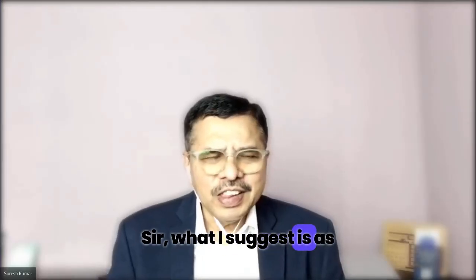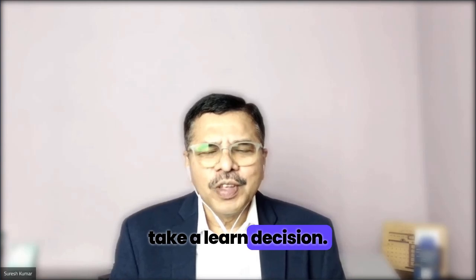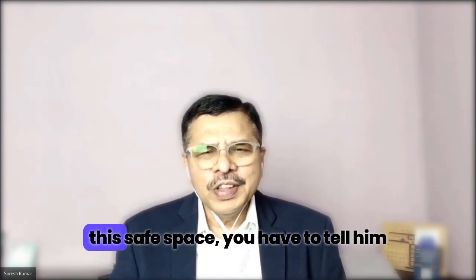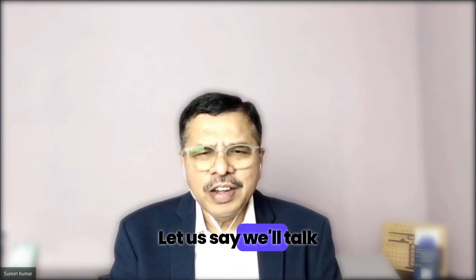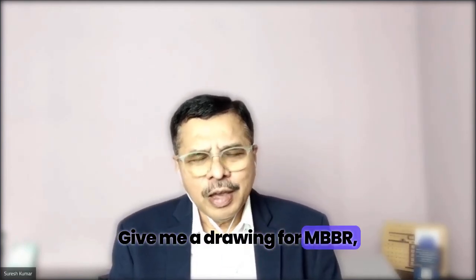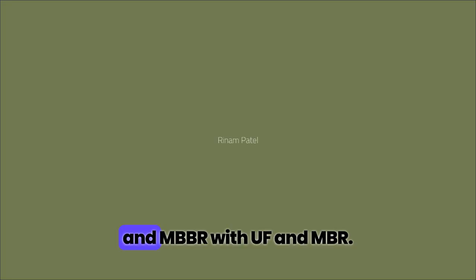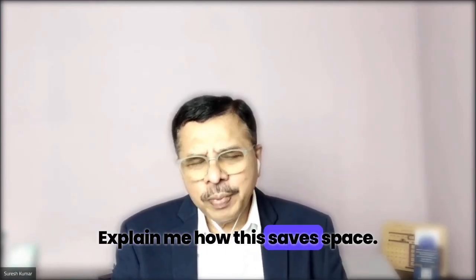Sir, what I suggest is, as educated people, we should take a learned decision. So whenever a vendor is telling you this saves space, you have to tell him, get me drawings for both. Same capacity. Let us say we'll talk about your 50 KL project only. Give me a drawing for MBBR, MBBR with UF, and MBR. Explain to me how this saves space.